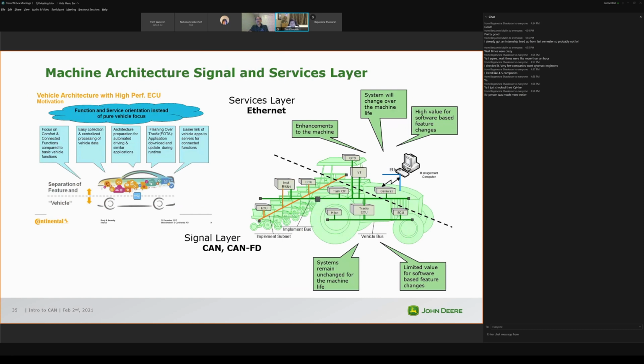Like a single connector, gosh, Subash, a traditional Ethernet connector that would last the lifetime of the machine is $20 for one connector. Yeah, exactly. When compared to CAN, it's only a few pennies, and you could integrate into an existing connector and it will work as long as you meet certain guidelines. And also, Ethernet is point-to-point, which means you have to add a switch. That's an additional hardware expense, and everything adds up.